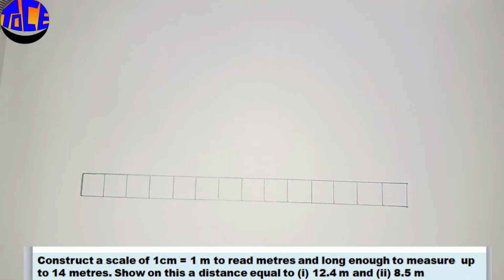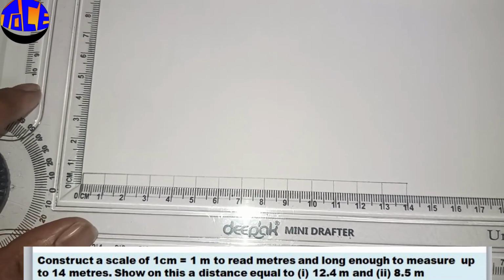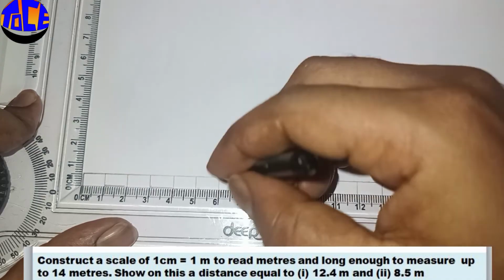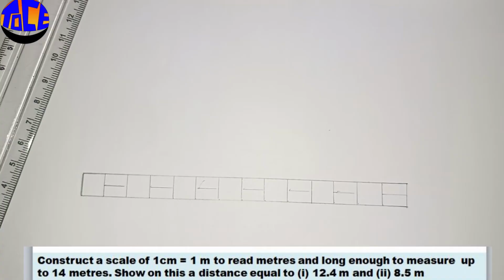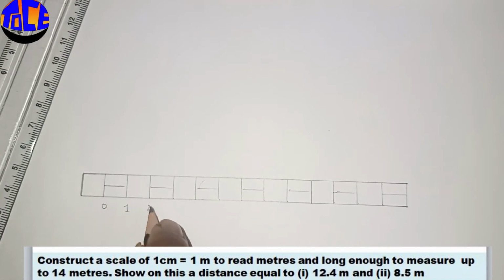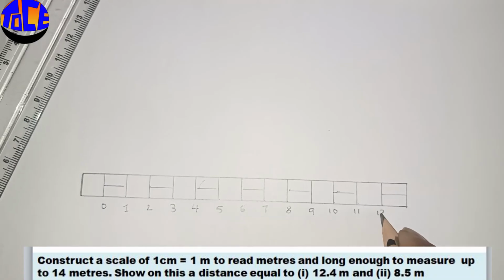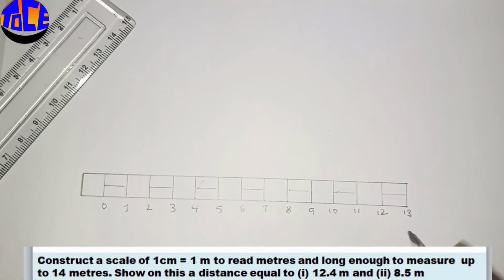Now let us draw the horizontal line in the center of the scale, so that it looks like a proper scale. Alternate boxes, drawing the horizontal lines, and here this will be 0, leaving one box. This will be 0, and this is 1, 2, 3, 4, and this is 13, and here this represents 14. So here we are having a 14 meters scale. So these are in meters.